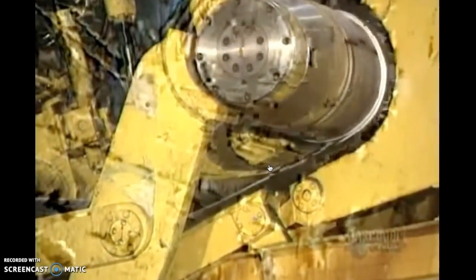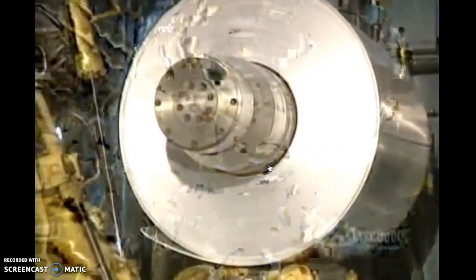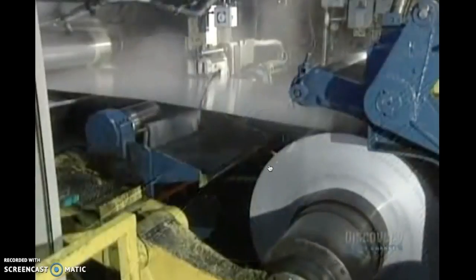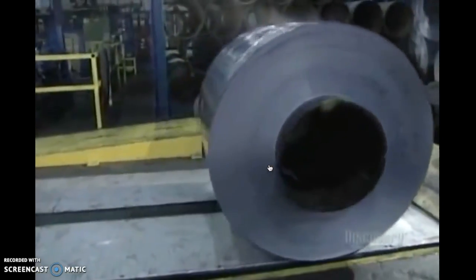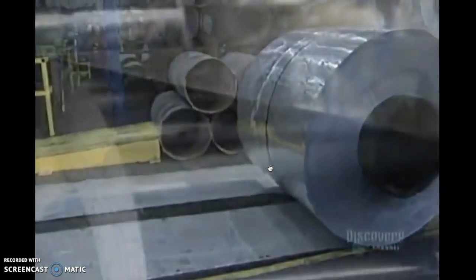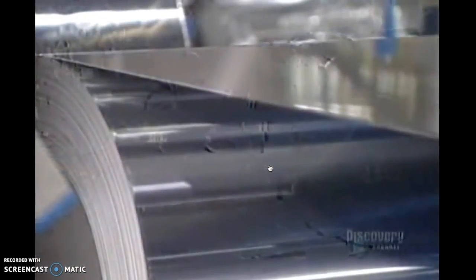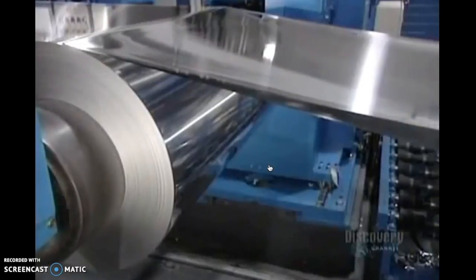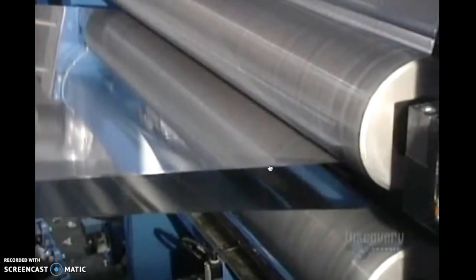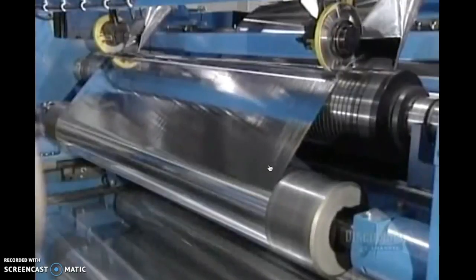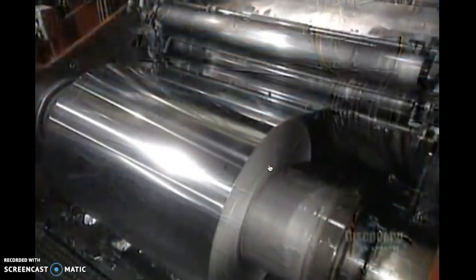It is sufficiently thin to proceed to spooling, where it spools onto itself before being sent to the cold rolling mill, where its thickness will be reduced still further. The aluminum sheet has become very thin now and risks being broken by the tension needed for cold rolling, so the sheet is doubled to avoid this breakage. One final reduction in the mill, and the sheet will have the thickness required by the customer.